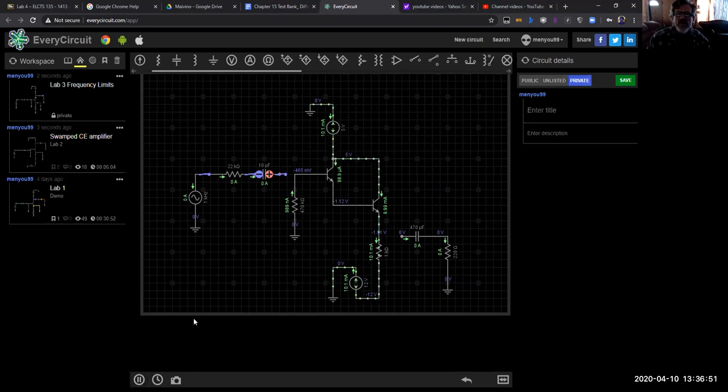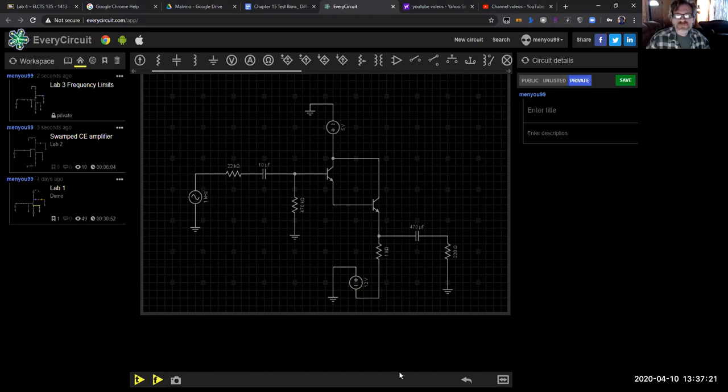So that's a way to quickly check, and throughout all these experiments, when we move forward, it's how do you make sure that we are DC? Again, you have to be DC biased, right? So make sure that your circuit is turned on. So let's go ahead and end that part. And now we'll reconnect our AC again and find out what our Darlington pair can do for us. So that's the hookup for it.